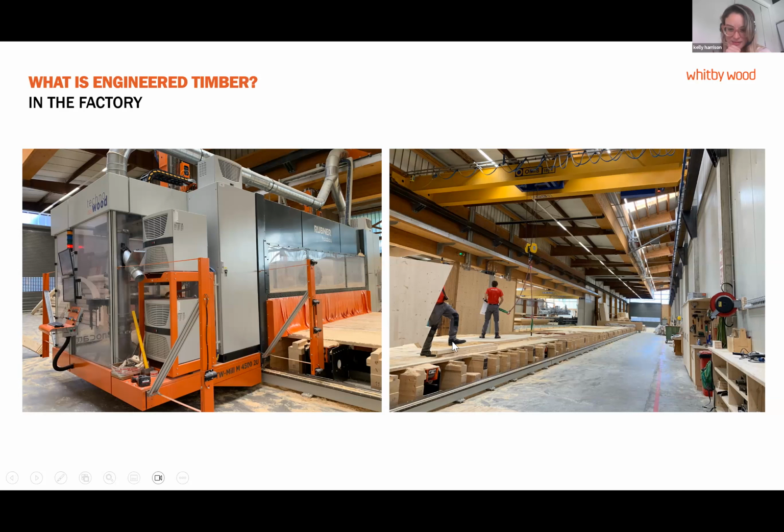They put the CLT panels on here, and they actually have a kind of tracking device that tells the machine at the end exactly where it is and what orientation it's in, and it will go along and cut exactly what it needs to less than a millimeter precision. So that is something you really have to think about as well, is the tolerances here, because everyone always gets told that you've got a 2 millimeter tolerance, but more often than not there's a 0 millimeter tolerance. And you have to remember that when you're designing things, you've got to think about how things are going to go together, because it's going to be exact. And particularly if you're thinking about refurbishments and existing buildings, and connecting into those, because they'll definitely not be exact.